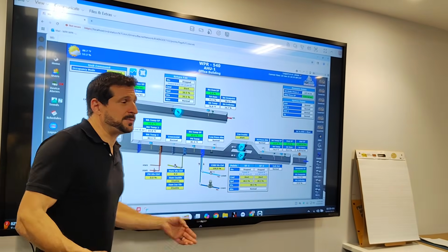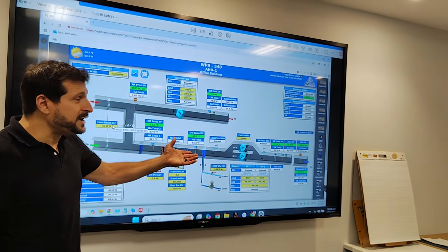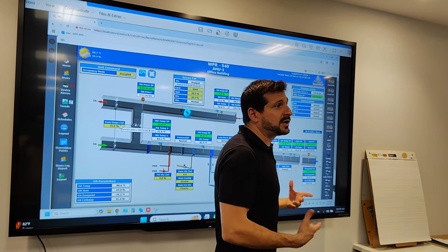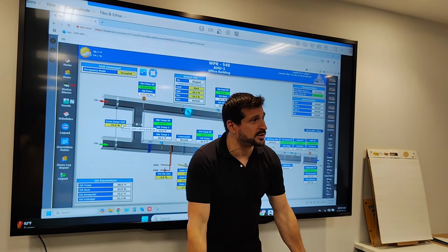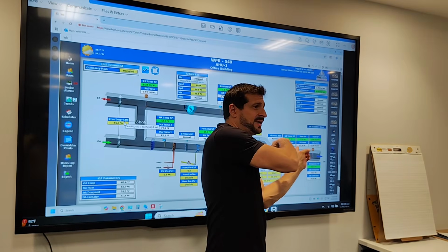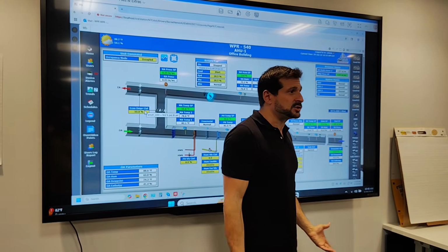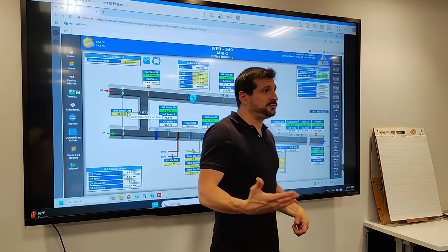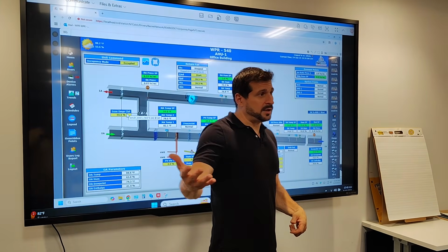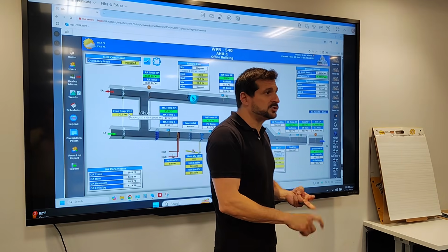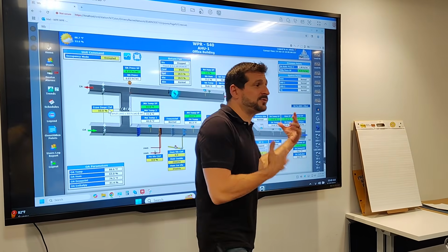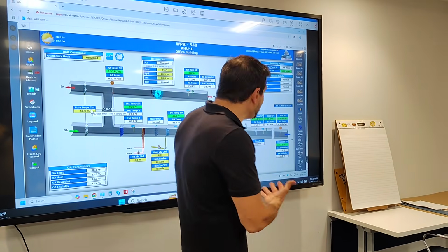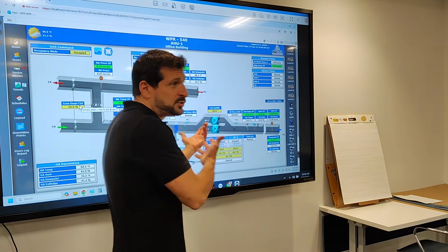That takes a lot more programming, and it takes control of the whole building. So you wouldn't have that shot right now, but if we took this over, we would have this as a fixed set point. We could come up with a number that would work, and then as you take over the rest of your floors, we would go back to this fan, and we could program that to be that intelligent design, which is actually what's in ASHRAE's guides. If you look at ASHRAE's ventilation index and ASHRAE's energy index, it tells you about all these different procedures that you can do that will decrease your energy consumption while still satisfying your space. That's how you do that kind of stuff. That you can't do with what you have right now.